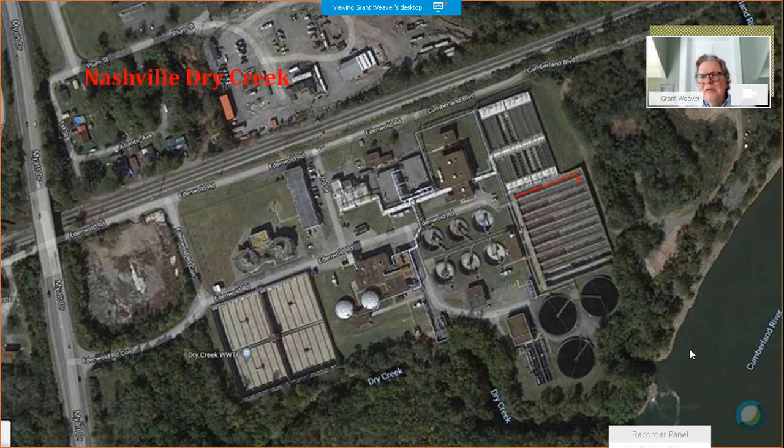The phosphorus went up a little bit because of that. Not a lot, but a little bit. And then this last zone, the air is cycled on and off. When they did that, I'm taking credit for it, the total nitrogen in that zone declined, and it looked to me like there was a measurable reduction in the electrical use, even though it was just one zone for that facility.